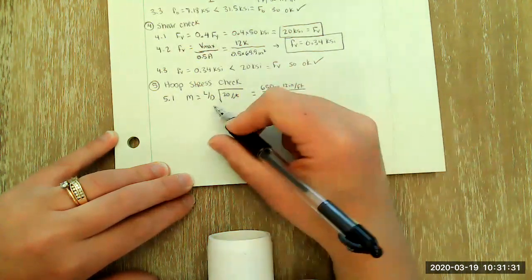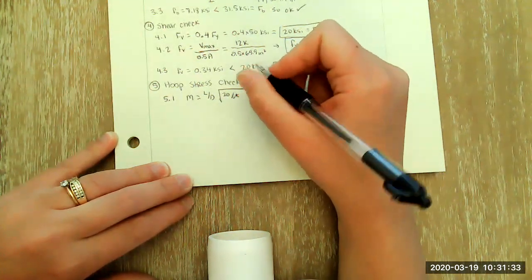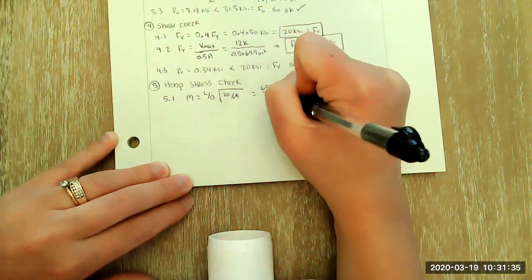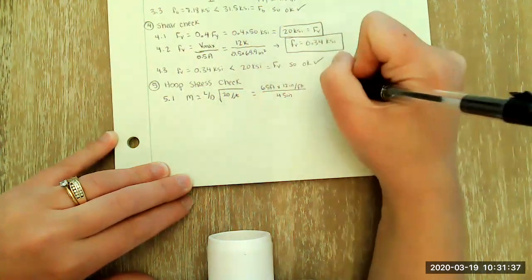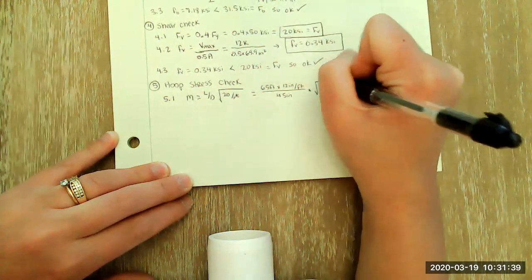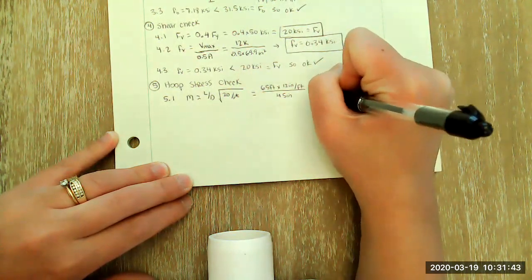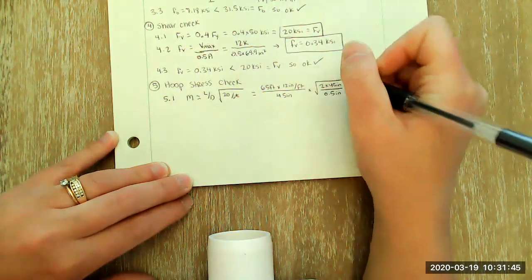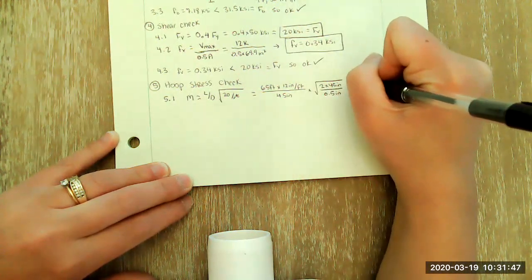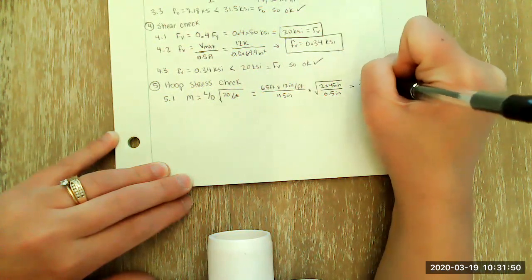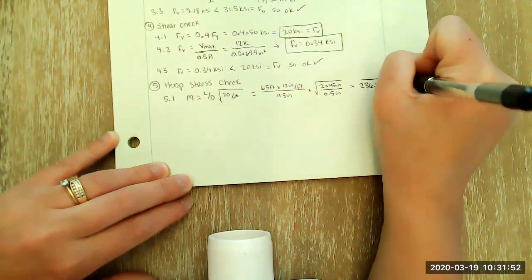And we're dividing that by our diameter of 45 inches times the square root of 2 times 45 inches divided by our thickness of 1/2 inch, which is equal to 236.2. That is our M value.